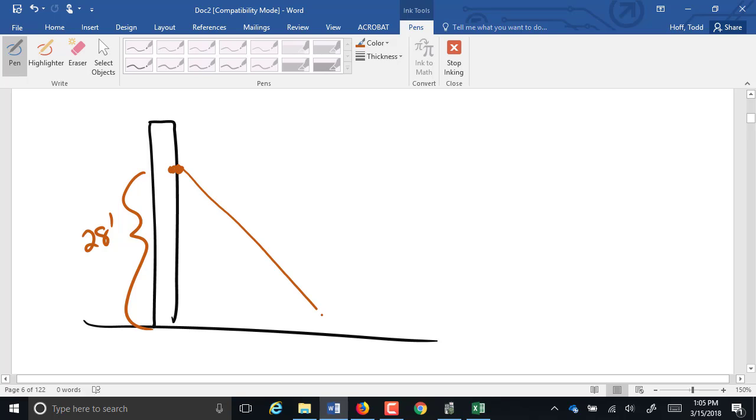You know that when you anchor it, the higher that angle is, the less effective that support is. The lower that angle is, in other words, the further we bring it out, the lower the angle will be, the more support that guy wire has. So let's say that our maximum angle there is 60 degrees. If it's more than 60 degrees, it's not going to hold.